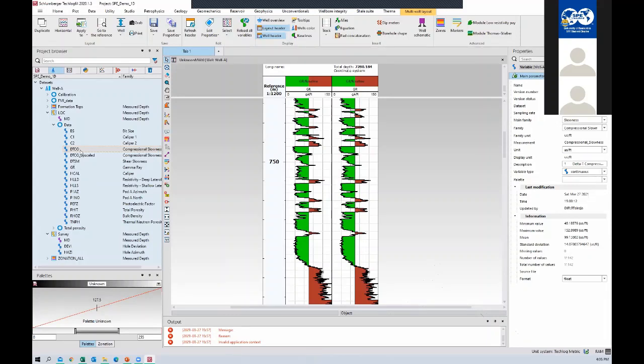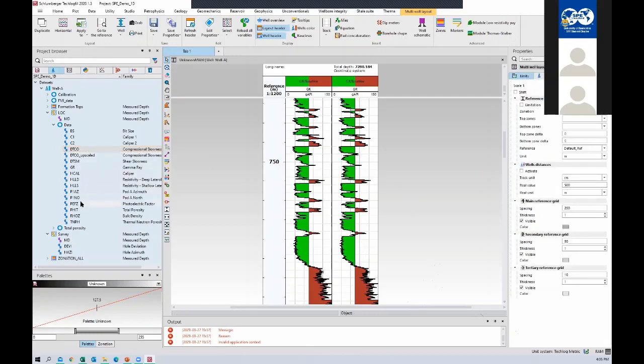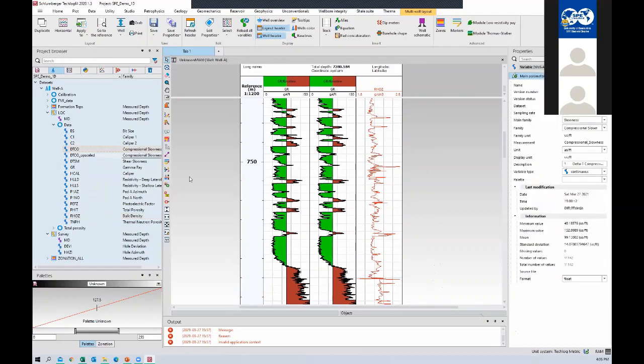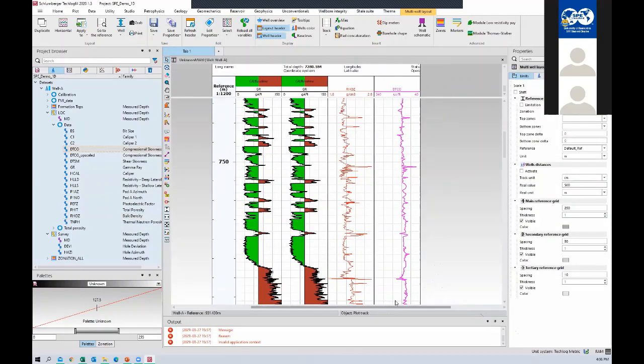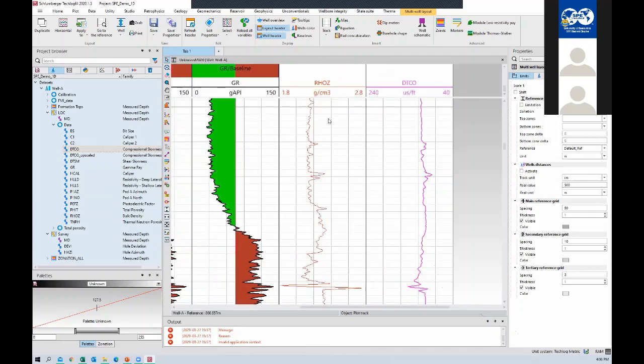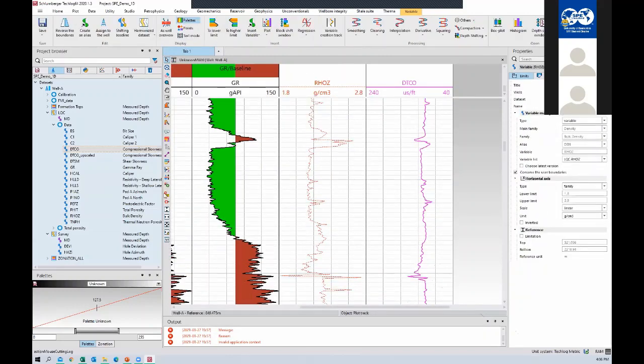So most of the time, as a geomechanics expert, I just QC whether the response of the log is proportional or not. Just to demonstrate how I QC, let's say over here you see density. Now density for this particular interval is high, right? Density is reading 2.6, and I see a spike in compressional slowness, right?